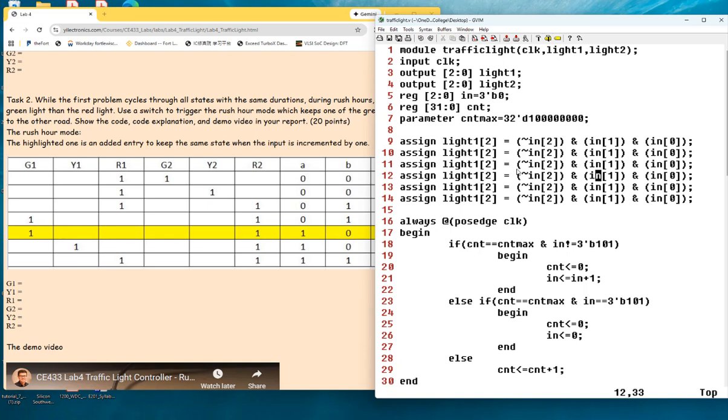just the input. So for the sub module, now we already have a traffic controller module. It's a sub module, right? It's a Verilog module, and we just have one single input, make it available for the sub module, and we directly connect that little input to a switch. Simply, then we're done. So we're just looking at or checking that input. If that input is 1, then we enter the rush hour mode. Then we use a totally different logic and counting method, right? Otherwise, we follow the old method, all right?